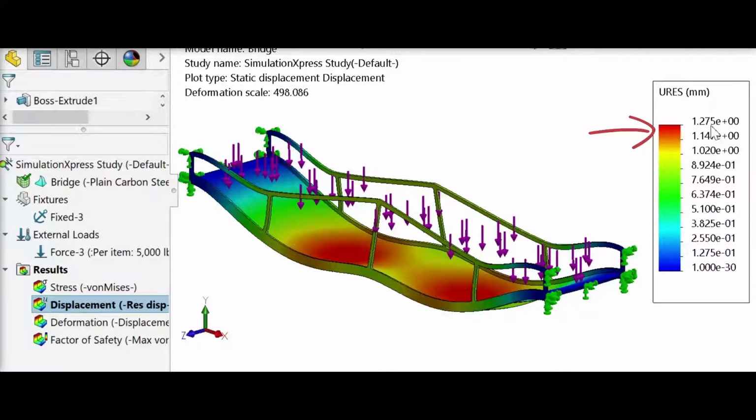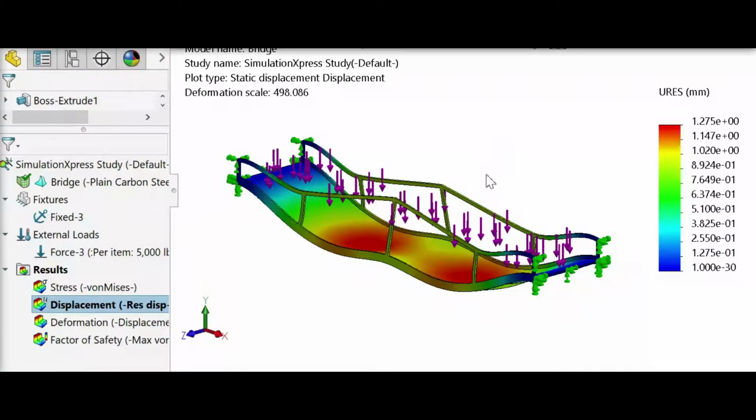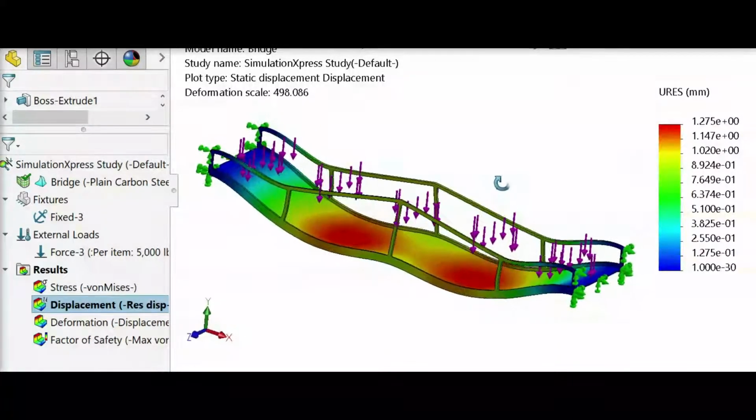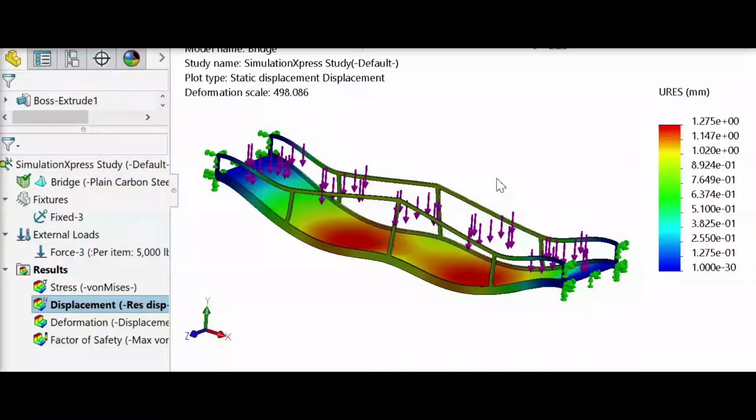In other words, we were able to reduce the resultant deflection roughly by 30% by increasing the section modulus of the cross-section. This is an example of a quick first-pass analysis to check deflection. Please keep in mind that we also have to check the stresses to make a well-informed design decision.